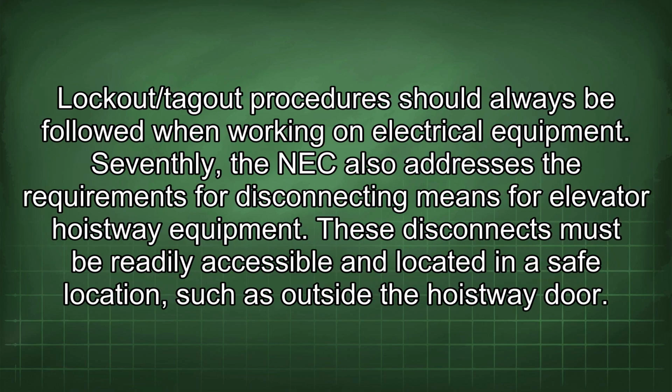Lockout/tagout procedures should always be followed when working on electrical equipment. Seventhly, the NEC also addresses the requirements for disconnecting means for elevator hoistway equipment. These disconnects must be readily accessible and located in a safe location, such as outside the hoistway door.